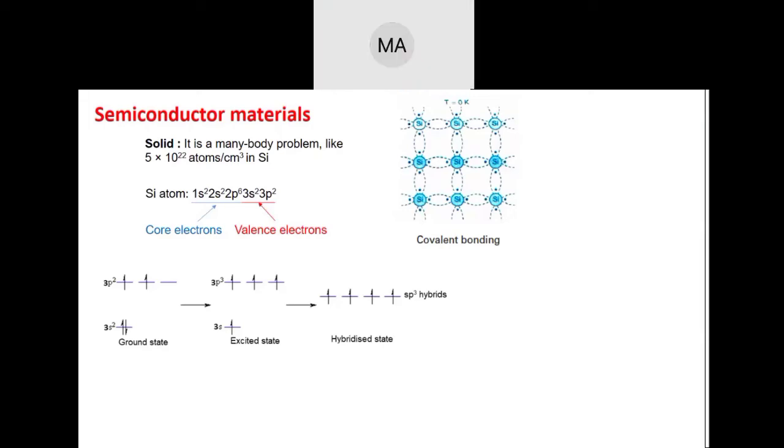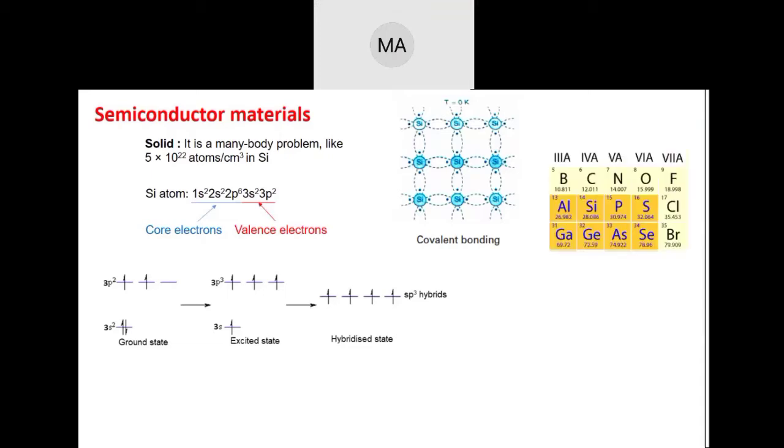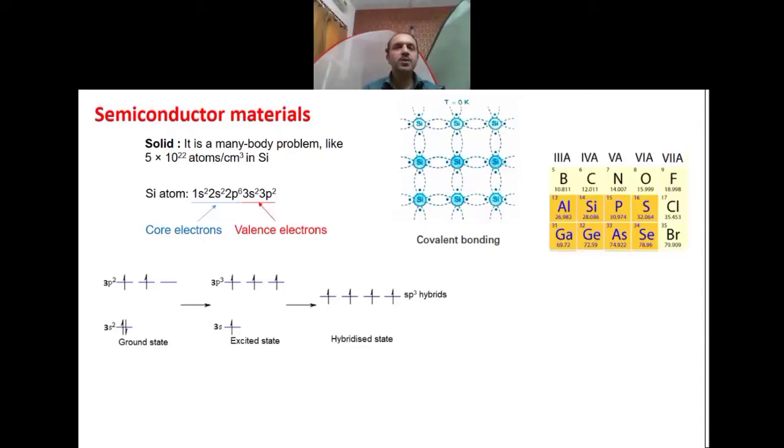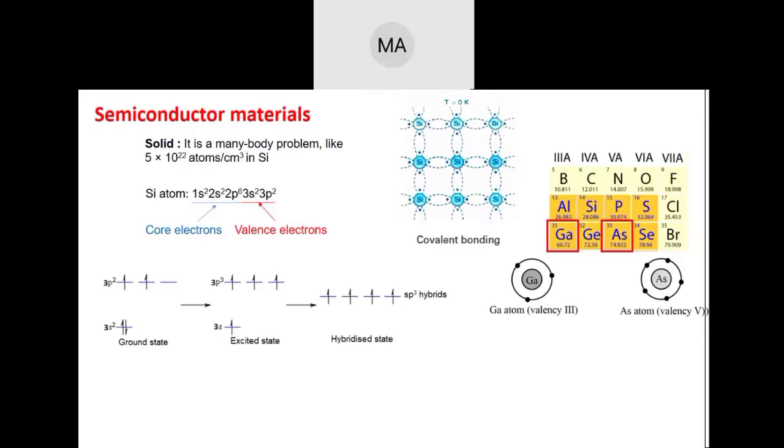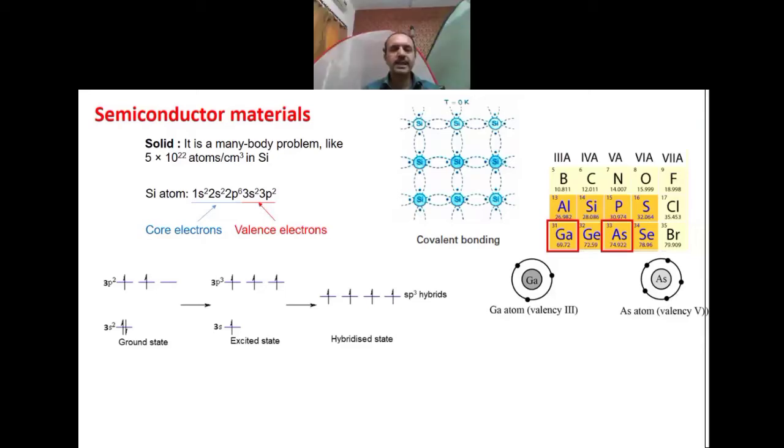Niklesh, there is my one question. Sir, you are talking about the specific contact resistance. So how can we get a low value of this specific contact resistance? Yeah, that's what I summarized in one of the slides. I gave you two things. One thing is the barrier height should be low. So you should choose a metal which, when you deposit it over the semiconductor, has a barrier height as low as possible. That is one criterion.